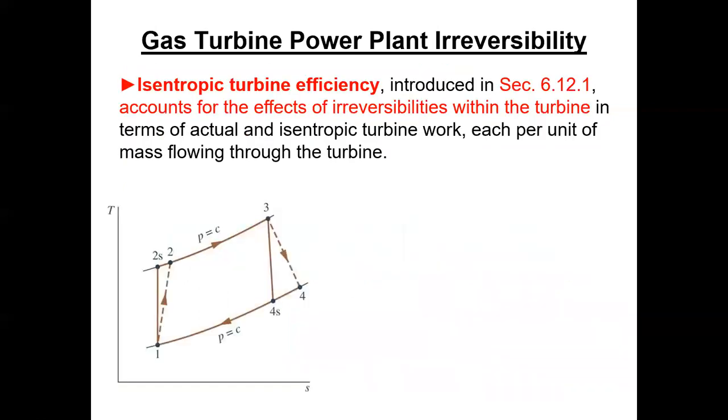Okay, on to the isentropic efficiency definitions. I think we went over this for the Rankine cycle, and basically it doesn't change. It's just, we don't have two-phase to worry about. Where's the saturation dome on this one? Is there a saturation dome for air? Well, air is mostly nitrogen. Is there a saturation dome for nitrogen? Can you make nitrogen liquid? Yeah, there is a saturation dome.